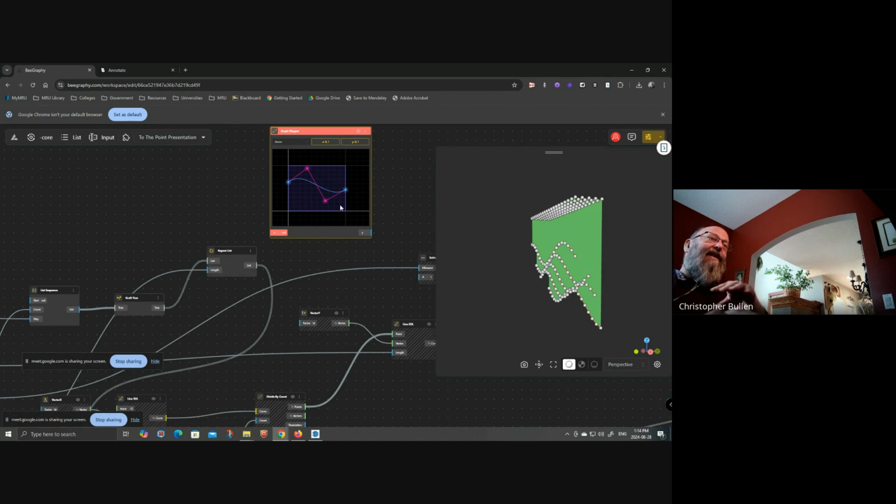So knowing that, that's where being able to work with parametric design, a lot of students get lost with, especially if I wanted to take a shape and morph it onto another surface. I need to parameterize that surface so that I understand how it's actually going to be mapped onto the surface. And parameterizing just means that I'm taking whatever values there are for the minimum and the maximum, I'm constraining them between 0 and 1, and then using that, because I understand 0.5 is 50, 0.75 is 75, 1 is 100, and so forth.